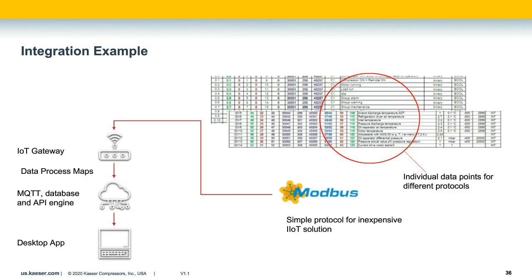Here we're going to look at a simple, low-cost example on how to implement an IoT architecture. Very generic overview, sufficient if you're interested in a limited amount of data points. So Modbus TCP, a simple free protocol. A lot of low-cost software is available, or even freeware that supports Modbus protocols. Low-cost IoT gateways that communicate to Modbus TCP, so a single-board microprocessor, such as a Raspberry Pi with supported Wi-Fi or LAN connectivity.